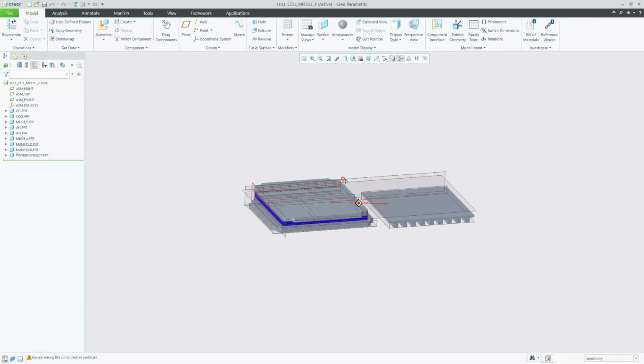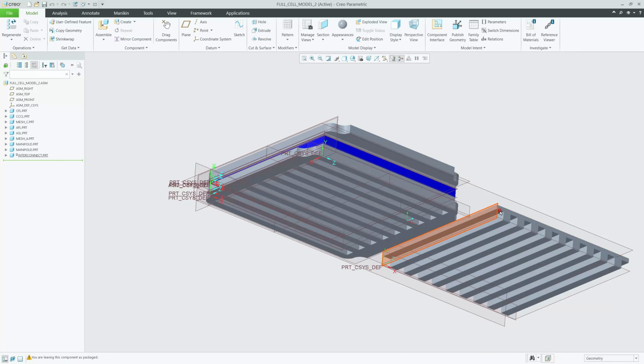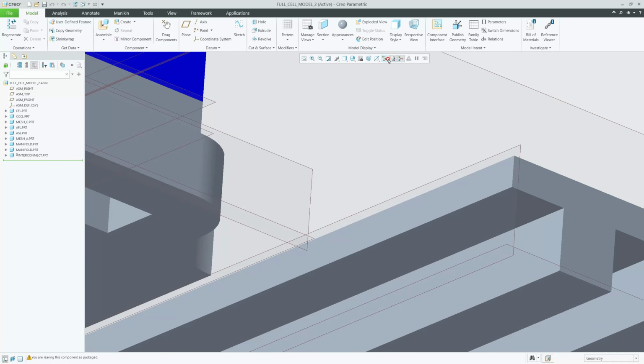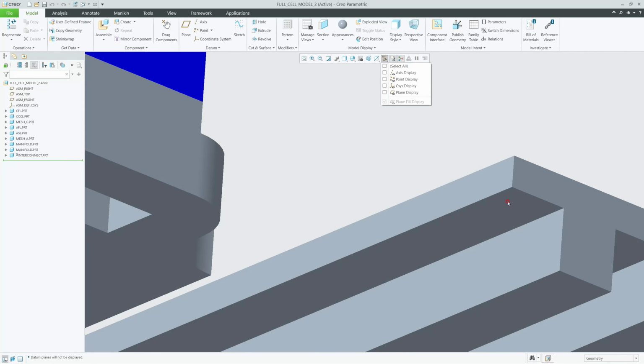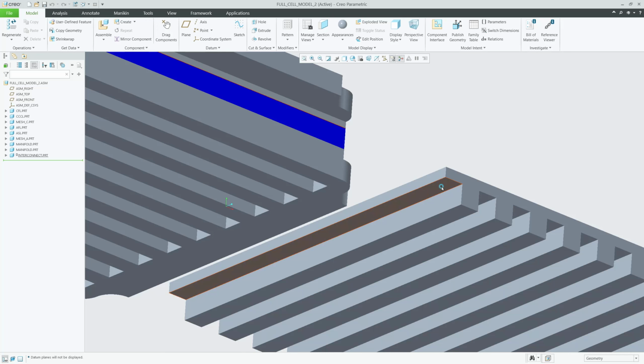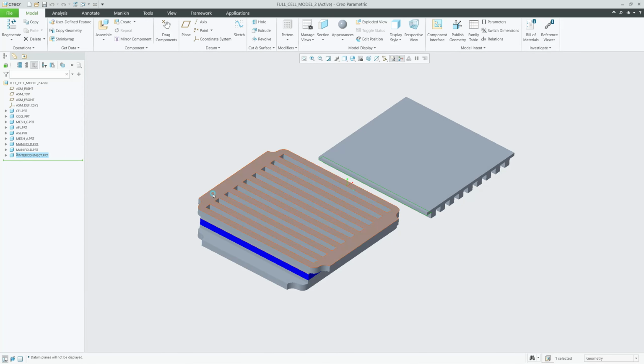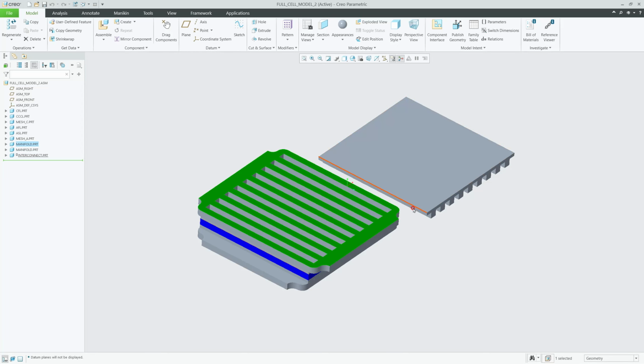Close this part, and now we need to assemble it. For assembling it, now the bottom surface should coincide with the inside surface, or this surface will coincide with the top of the manifold. So we can have, this is easier, so we'll take this, and at the top of the manifold we'll make it.